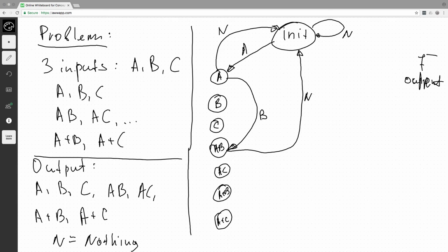All right. So in this case, when we are in the state A, and by the way, this could be an incorrect transition, because we don't want to go back to initialization once we are in state A, because it would not allow us to move on to B. We know that a press of the key is immediately followed by the release of the key.